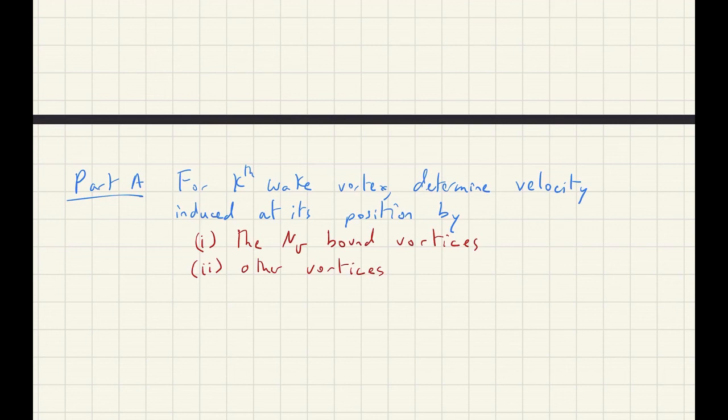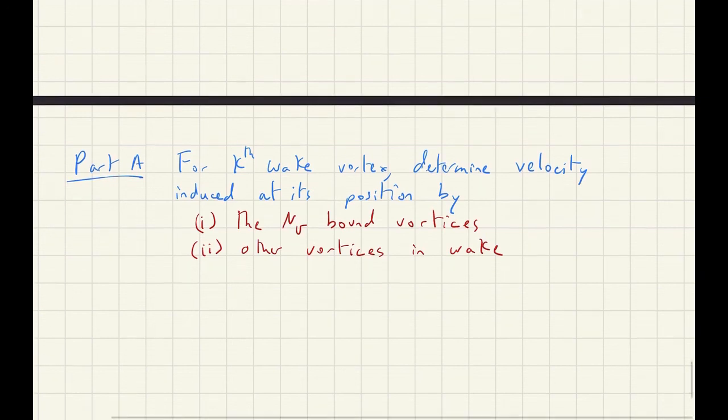So each vortex affects the other, and it's sort of all coupled together. We don't really have to find the influence of the kinematics on the wake, because in the inertial frame of reference we're using, we are moving the wing. So this is how we get the displacement between the wing and the wake from the kinematics, through moving the wing and not moving the wake.